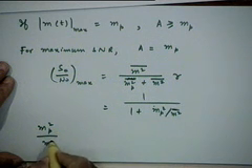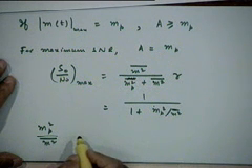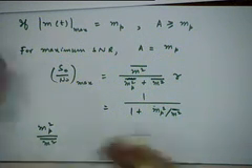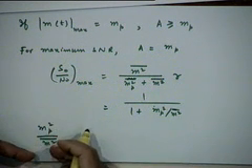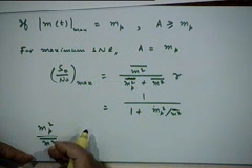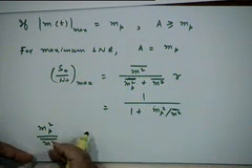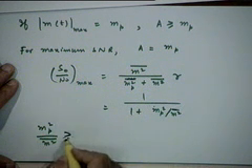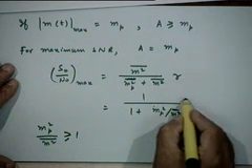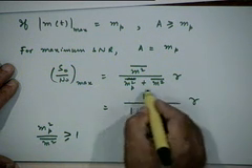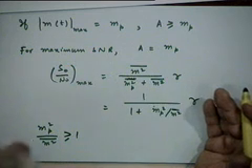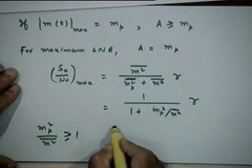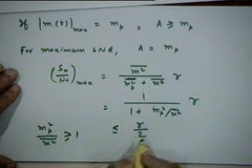Would it be less than 1 or more than 1? More than 1, because m_p denotes the peak value and m square bar is the mean square value. This is the square of the peak value, this is the mean square value. So obviously the peak to average ratio is typically going to be greater than or equal to 1, right? So this obviously means that the factor by which the effective SNR gets reduced is going to be less than or equal to gamma by 2.